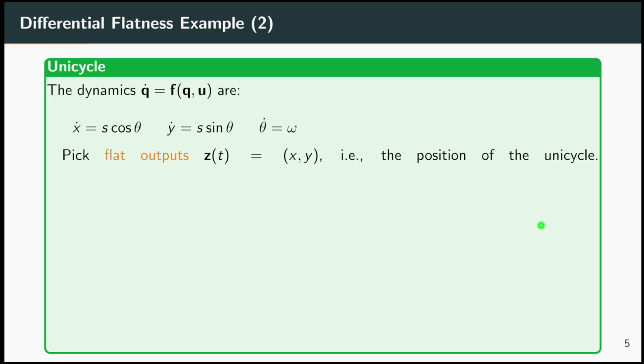There's a little bit of magic in these differentially flat systems, but you have to pick something for this latent space z. Here I will just propose that we use the position. It's slightly less than what the original state space was, where we also had the orientation. Now what we're looking for are the mappings or functions that I proposed earlier.